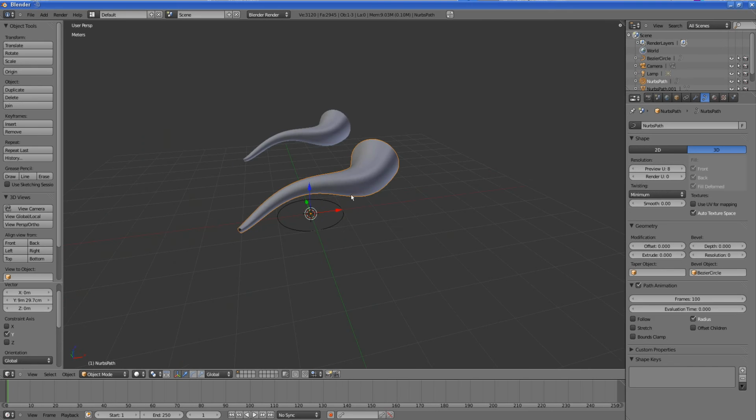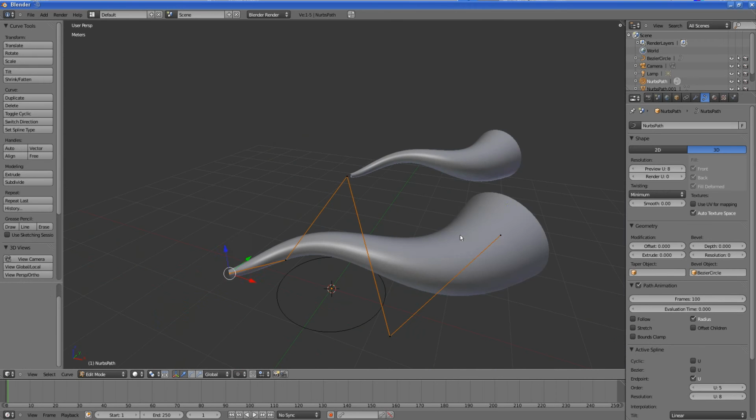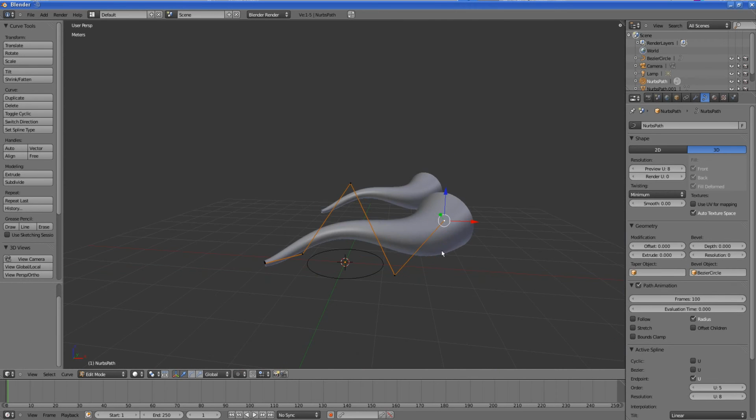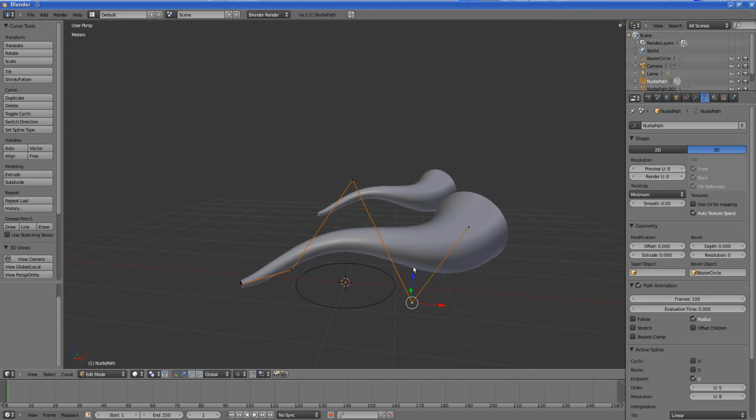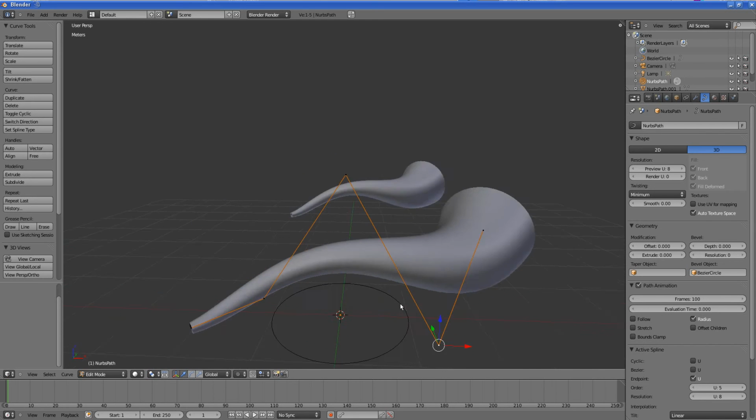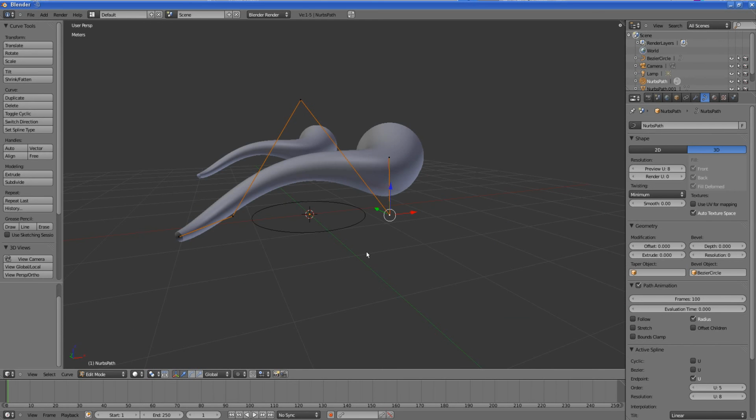You can do more things with this curve. So far we have seen Alt S to shrink and flatten this control vertex. Every control vertex also has a tilt operator. The hotkey is Control T, and to clear the tilt it's Alt T. So let's select this control vertex and press Control T and then move the mouse.